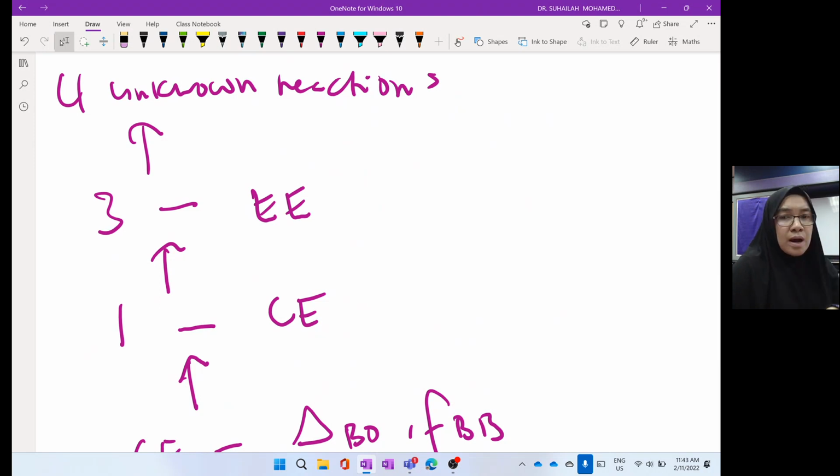So that is why the flexibility method takes place. Okay, so when we apply the flexibility method, we will have the compatibility equation to solve for the redundant.